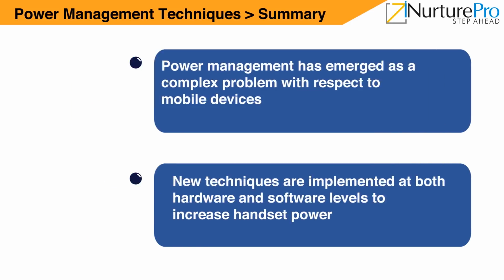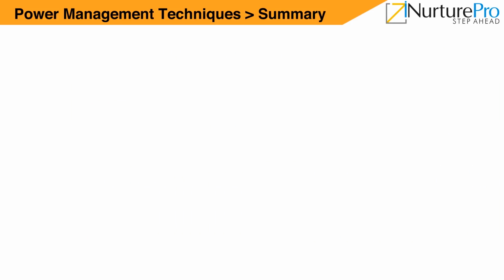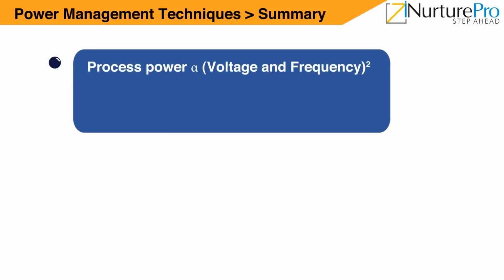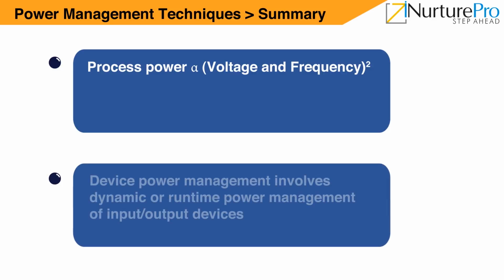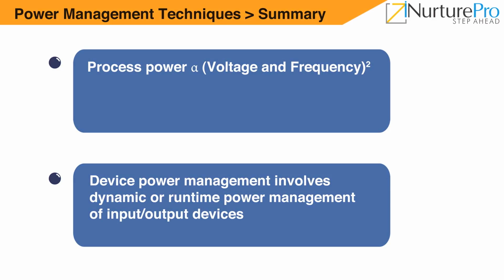Modern processors support techniques such as dynamic frequency and voltage scaling, which enables mobile operating systems to make adjustments in processor frequency and voltage dynamically on the basis of the demand of computing power needed to complete a running process on the processor. Runtime power management automatically assigns input or output devices into a low power state that they support when a particular device becomes idle at runtime.